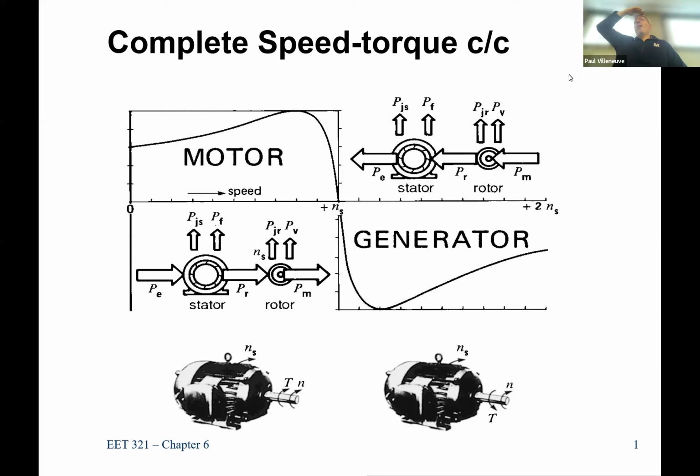Now, that's also a problem because one of the things that happens during regular operation of a system is you get faults. And if you get a fault nearby a wind turbine, what happens? The voltage collapses. And now the wind turbine, which was helping to support the grid by providing some power, is no longer able to provide any of that power, right? Because the voltage is really low, so it's not able to get enough magnetic energy to create this magnetic field.